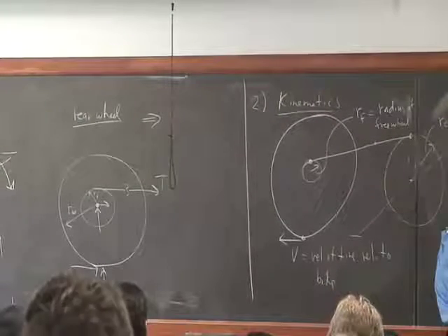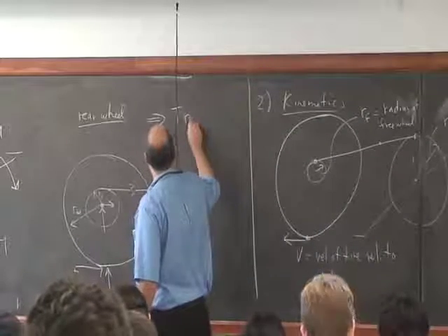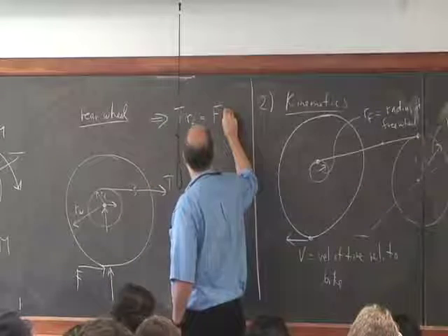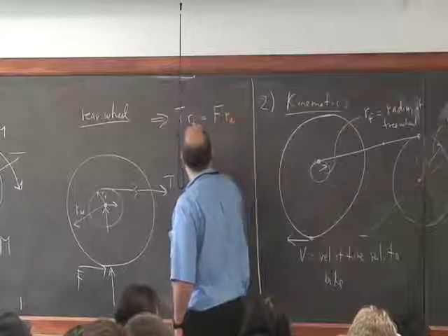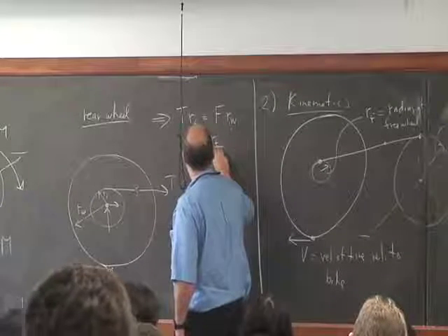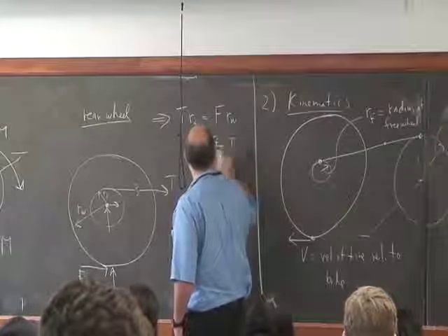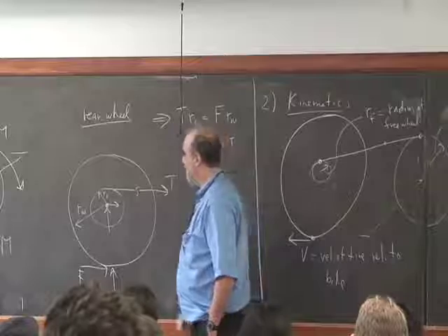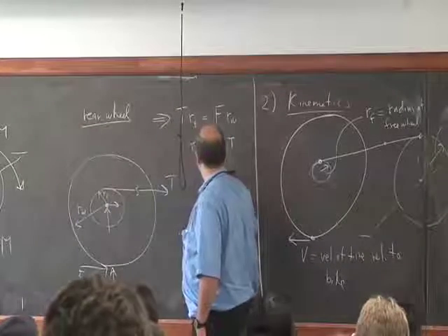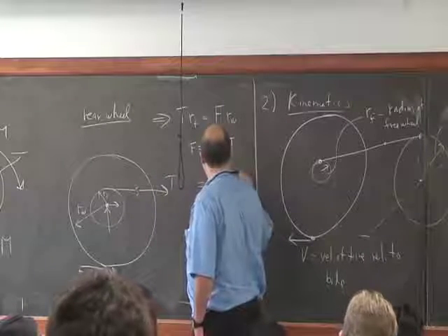which is the sum of torques about the origin equals 0. We get that the torque times the radius of this free wheel is equal to the force times the radius of the big wheel, which means we can write the force is equal to the radius of the free wheel divided by the radius of the big wheel multiplied by the chain tension. But the chain tension we already figured out is this moment divided by RC. So we have this is RF divided by R of the wheel, RC times the moment that's applied.